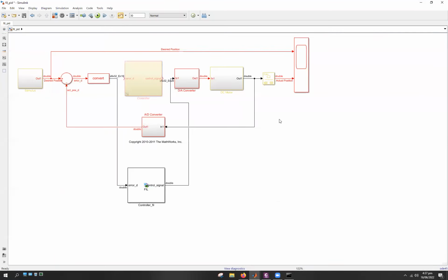But if our model gets complex enough and we start incorporating more and more complex algorithms for our controller for a plant, the processing time gets greater and greater, and the simulation environment is not sufficient or robust enough for those processing demands, and we need external hardware to perform that advanced algorithm processing for us. In that scenario, the FPGA in loop setup becomes very, very important.